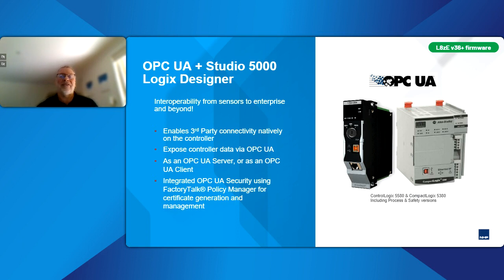Anyway, there's a whole lot of stuff in the knowledge base on how you go about doing that. But because we've now added OPC UA on the controller, what's important is that they've enhanced the latest version of FactoryTalk Policy Manager, 6.4 and above. It supports, which I should say on the slide here, but I don't, managing OPC UA security, certificates and encryption and stuff like that, turning it on and off. So you only need one bit of software to manage that security.